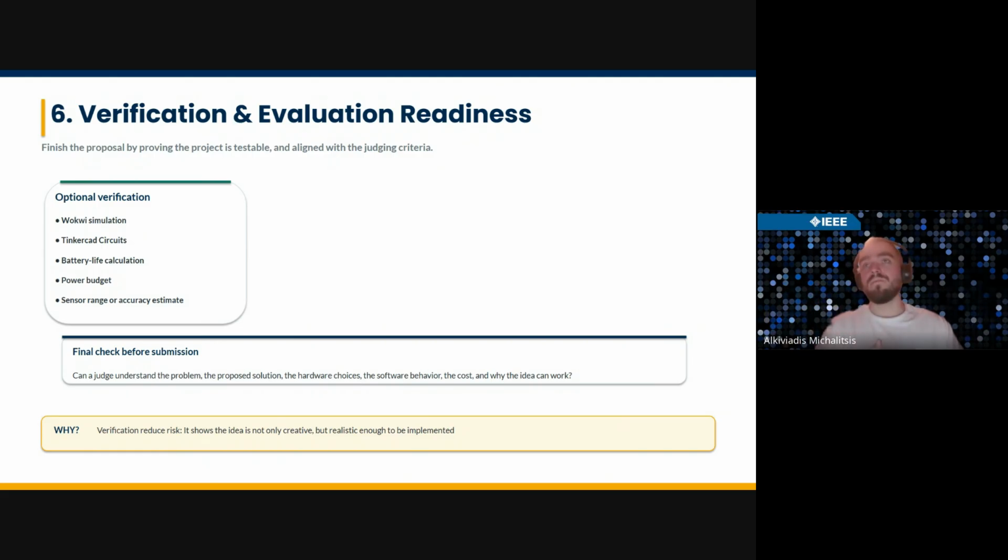You should think, okay, I have this information regarding this sensor. It can do this, but what is the real need of my implementation? If, for example, I want to see a distance and the distance is always like 5 centimeters, I don't need a sensor that can read up to 5 meters. This is redundant. So we need to select something that is a little more than what we want, but it's the most inexpensive choice based on what we need.